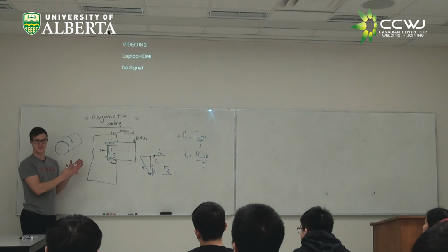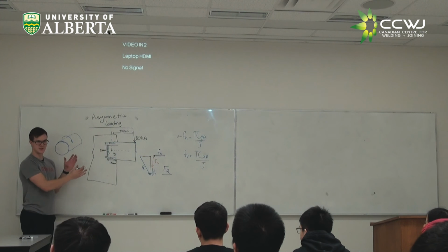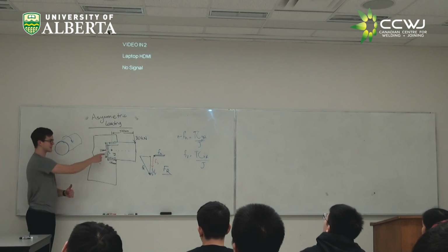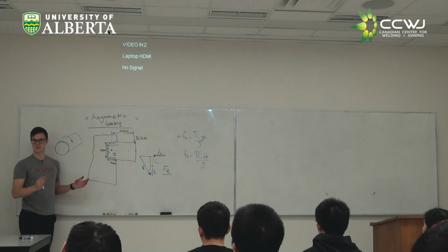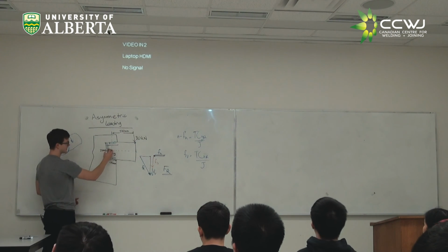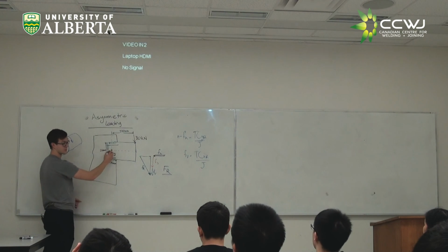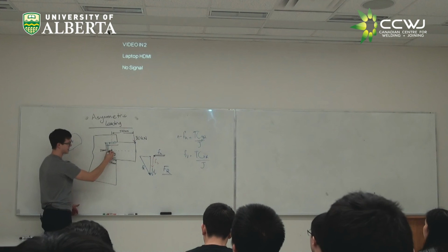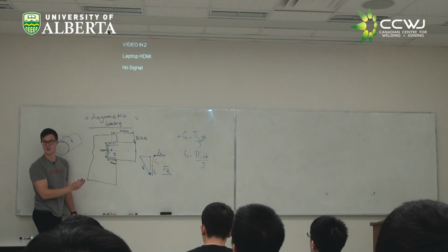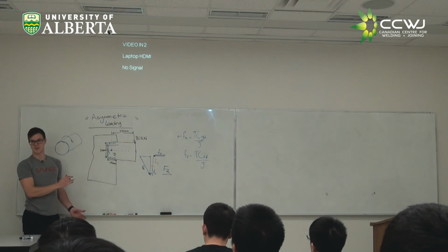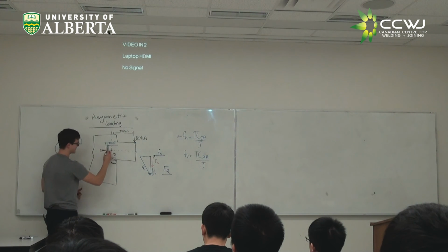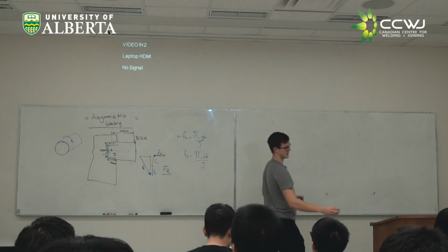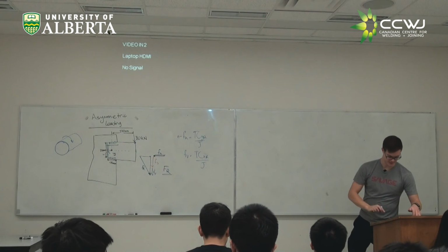The way that this is handled in this sort of situation from the handbook and the codes is they look at whatever point of the weld is furthest from the center of gravity, kind of the worst case scenario. So in this case, our furthest in our horizontal length and our farthest in our vertical length, we would have to calculate where this point of the center of gravity is. Those equations are given. Because we're running out of time a little bit, I'm going to help you guys out here and say that this ends up being, let me just make sure I double check the number. I think it's 93.75 though.